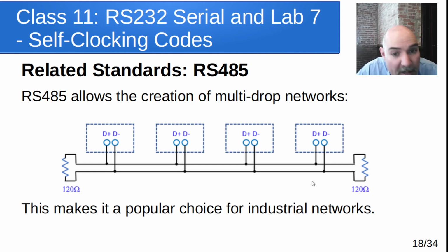One thing that's important on RS485 networks is this terminating resistor. And the reason for that is when these get taken over and stuff gets put on there, you don't want things hanging out that make them act like an antenna. And you also don't want the signal hitting the end of the wire and then bouncing back and forth. So they have what's called a terminating resistor that's usually put at the 2 end nodes on the network. Those are usually like a 120 ohm resistor.